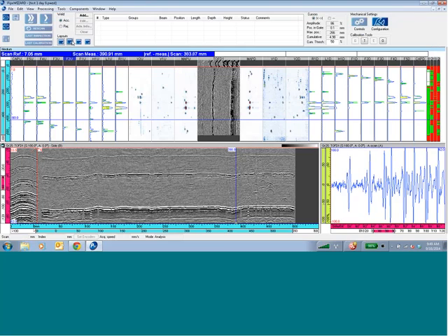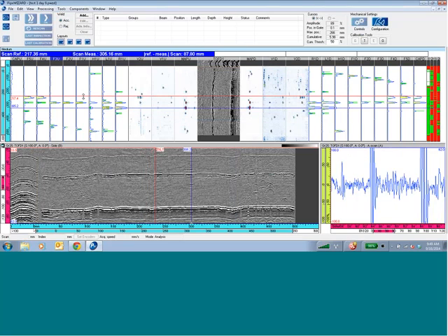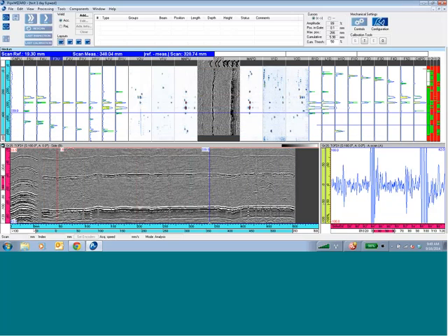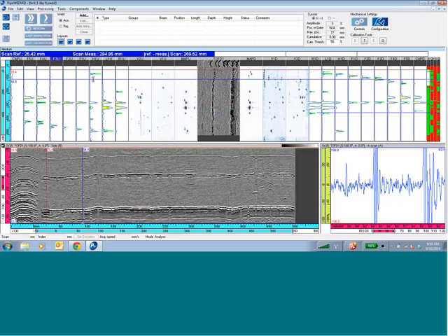We have different displays, so often an operator will set up two or three, up to four main layouts so he can manipulate this data very quickly, look at various things, and do the analysis at a rapid rate. You can see here, if I highlight a different channel, we're able to look at many pieces of information very quickly. If I just position my cursors, we're basically looking between those cursors. If I make it very wide, I'm actually looking at everything in between. It's going to go to the biggest. But if I hone in on a certain reflector, right now I'm looking at just this one channel I highlighted and only the things between my cursors. We're able to get quick information.